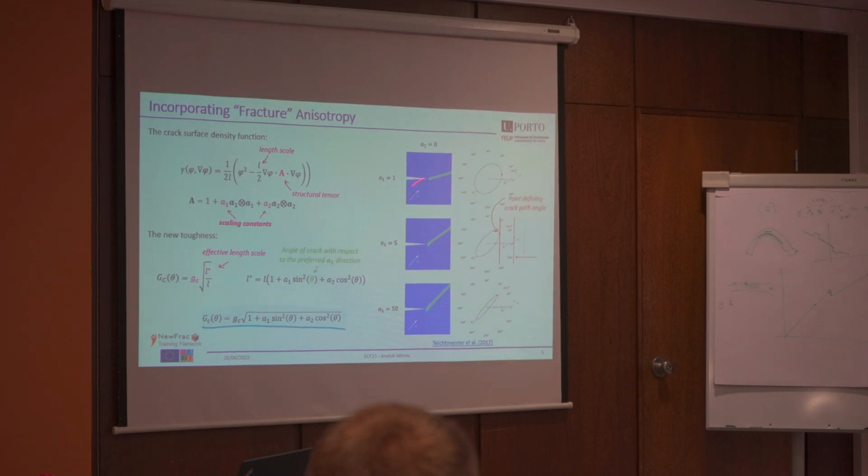And that is presented here in this very nice plot from thin-ply work. You can see for a certain inverse toughness plot, if this CT specimen is loaded in tension, the path that the crack will follow, so the angle it will follow, is given by the point of the tangential intersection with the line following the load path. And what is mainly of interest in this plot is to show the influence of the scaling constants. As the scaling constant changes its value, you get a different form of the inverse toughness, which essentially means you get a different toughness form.